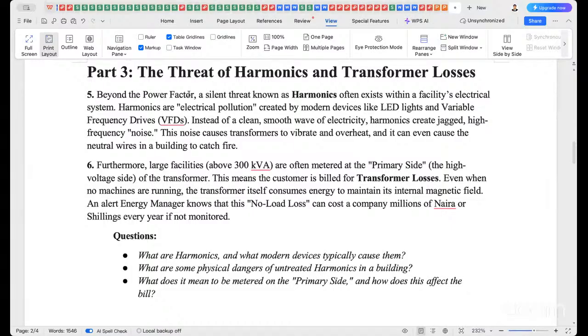We've talked about power factor, and we've talked about demand, which is something we need to look at. For example, in a manufacturing plant, like the case study we had, instead of putting up all the load at once, why not cascade your load? Put on a pump first, then 30 minutes later start up sequentially, which is why you see the plants doing that.